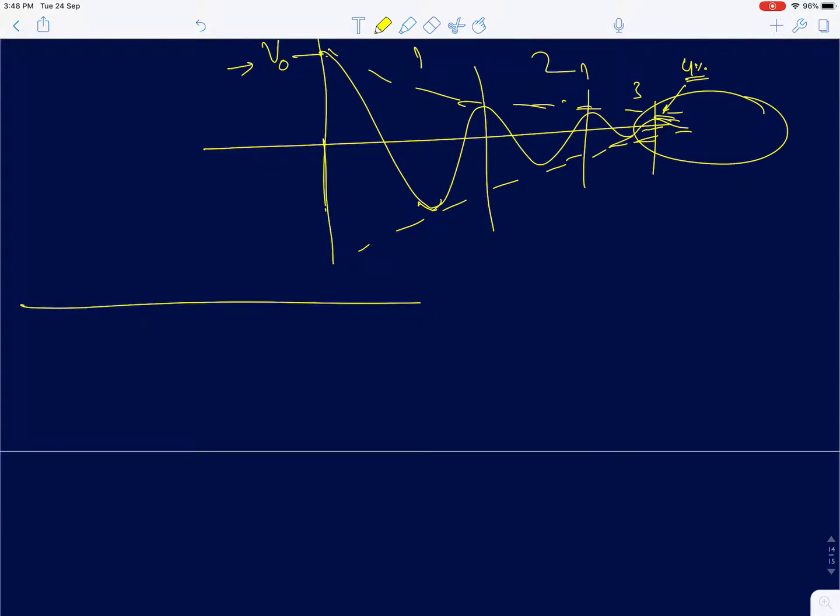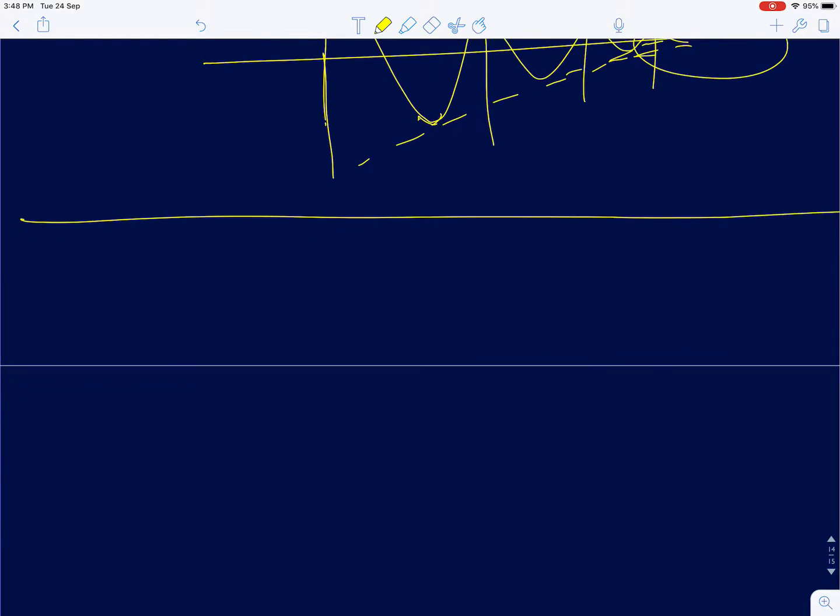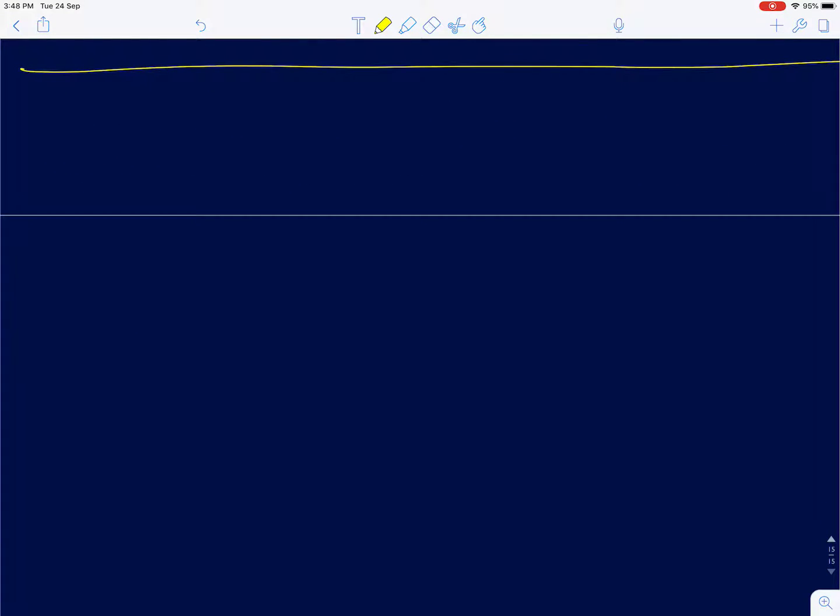Okay, so that's how, given an impulse response, you can measure the Q of the parallel RLC circuit. And if you remember, this is time domain. From time domain, we are estimating the Q of the parallel RLC circuit. Now, in case I give you the frequency response, you can also estimate the Q of a resonant or a second order parallel RLC circuit from its frequency response.